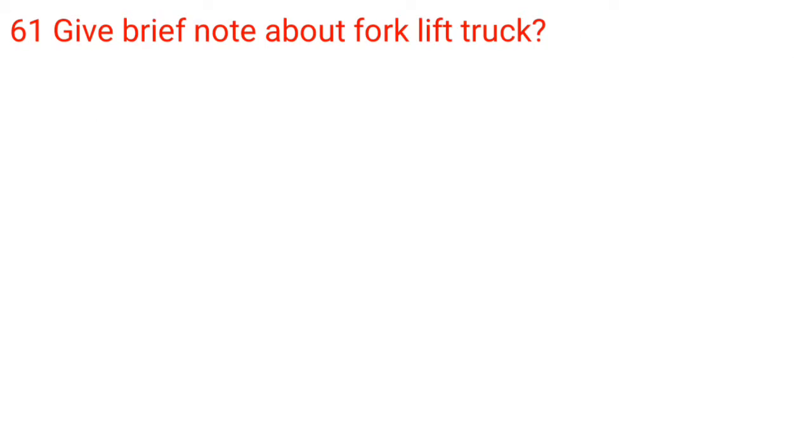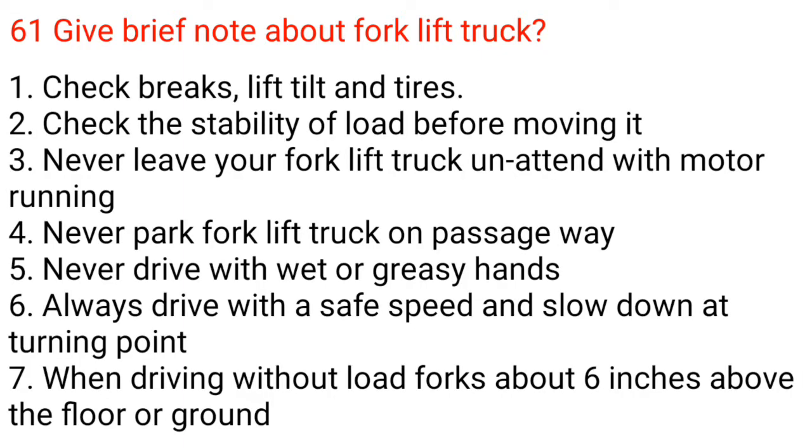61. Give brief note about forklift truck. 1. Check brakes, lift, tilt and tires. 2. Check the stability of load before moving it. 3. Never leave your forklift truck unattended with motor running. 4. Never park forklift truck on passageway. 5. Never drive with wet or greasy hands. 6. Always drive with a safe speed and slow down at turning point.